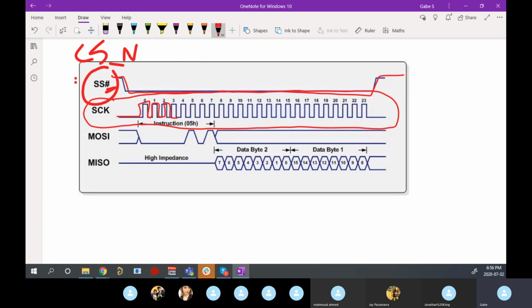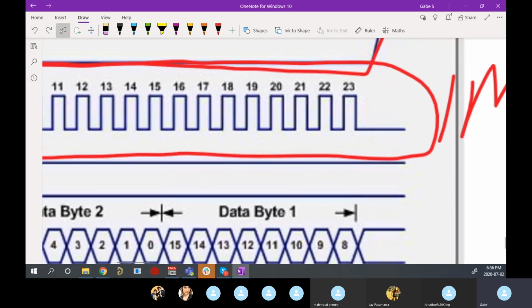And the frequency of these signals is basically referred to as the speed. So if I'm toggling the clock at 1,000,000 times a second, 1 megahertz, it's going up and down. That means the period of each one of these little things is 1 microsecond. So that would look something like this, from here to here, and then it would start again, right? That whole thing is about 1 microsecond. So it's really, really tiny.